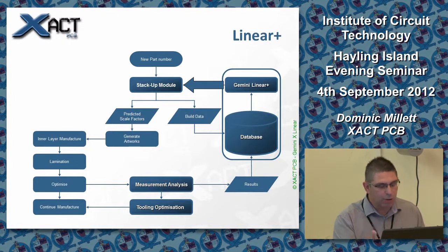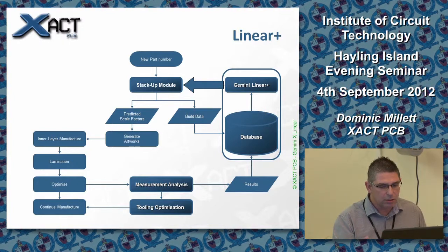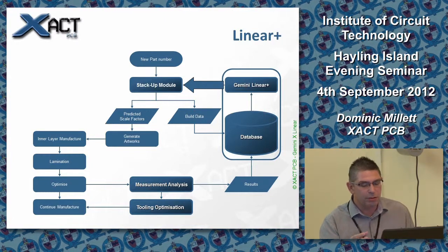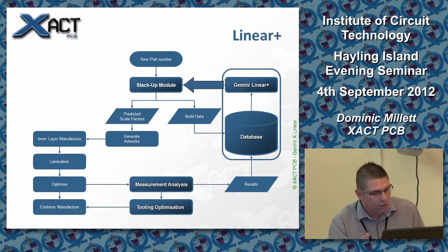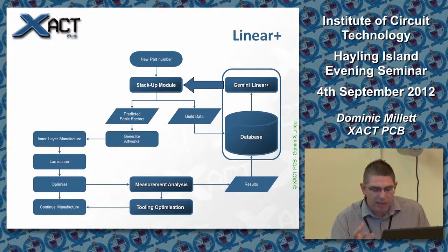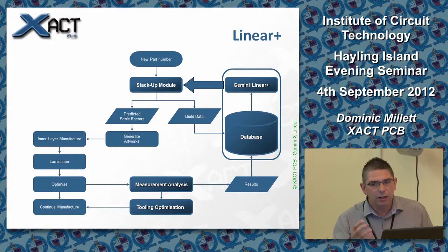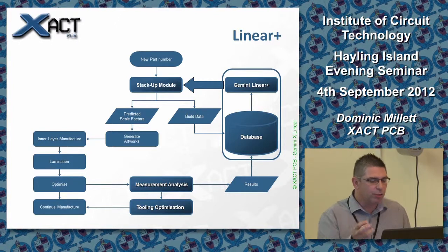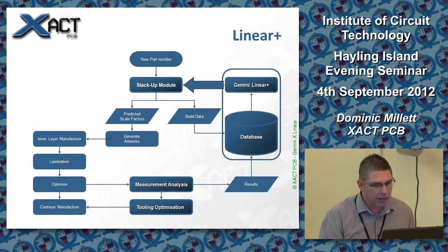You go through the production cycle, measure panels, that information is matched together, stack-up and measurements into the database. The predictive engine works on all of that information to give you trends, to give you statistical analysis in order to produce predicted scale factors for the inner layers.